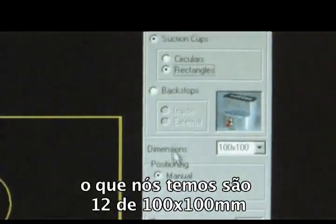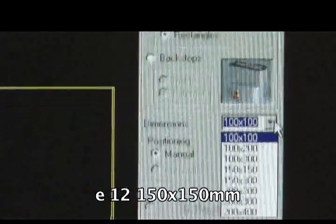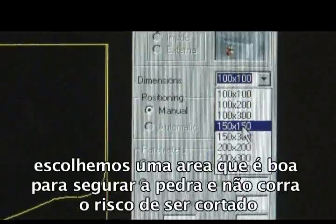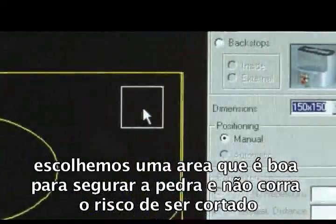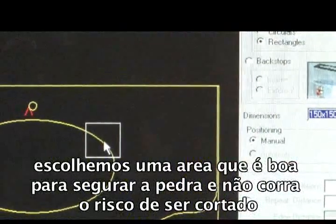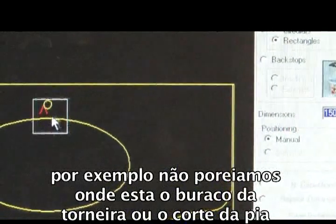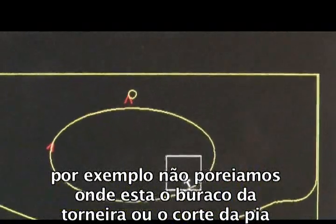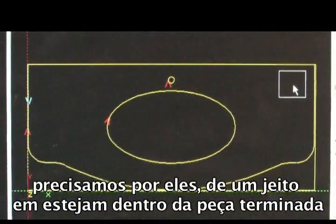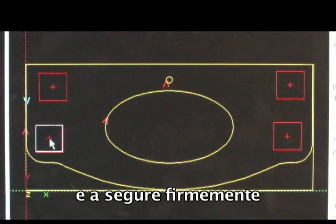The suction cups we have are 12 100 by 100 and 12 150 by 150 suction cups. We'll start with the biggest suction cups, and we'll position them in an area that's good for holding the piece, but also is good for not cutting through. For instance, we would not put a suction cup under a tap hole or on a cutting edge line for our sink, or for that matter the outside edge here. We need to position these so that they're inside the finished piece and holding firmly.